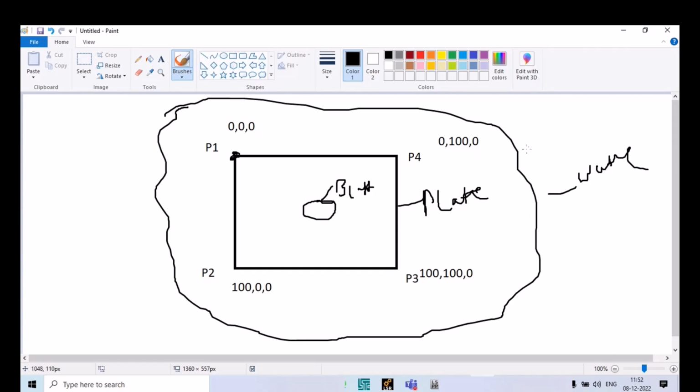I want to see in the fluid the deformation on the plate. Basically, in ALE cases we do not directly see any deformation on the parts. In this kind of case, when we perform a simulation, we see the effect of that deformation, the exact impact happening from a blast or something.